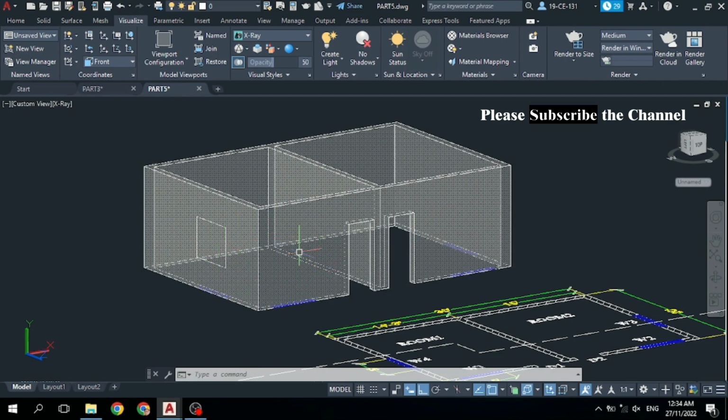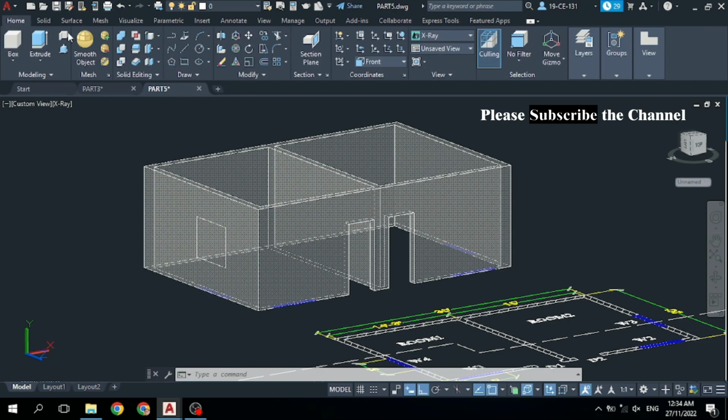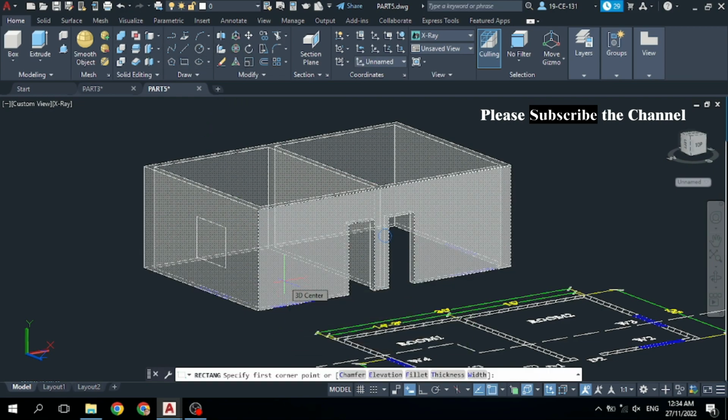Now I would like to use another method to draw this window frame. For that come to the Home menu and select this Rectangle and cursor your mouse at this face, and then select this as your base point and go upward, cursor your mouse in this direction. Your window is 3 feet above from the bottom, so type 3 feet and press enter.